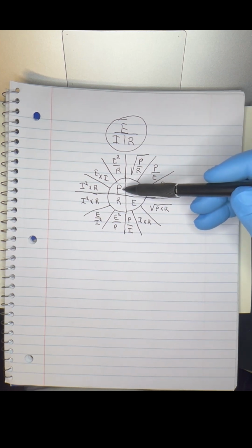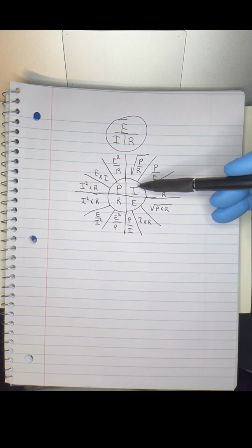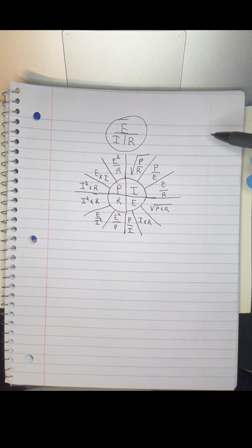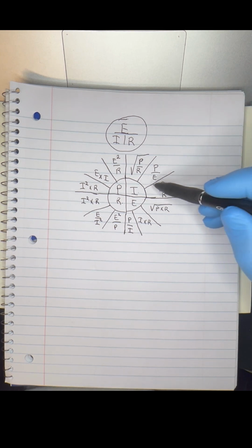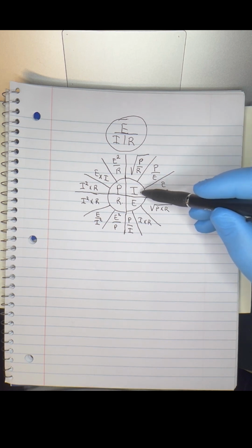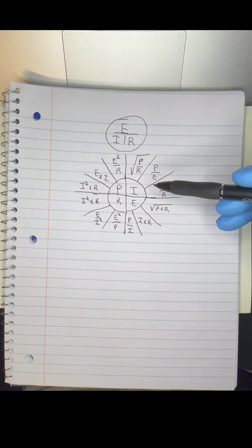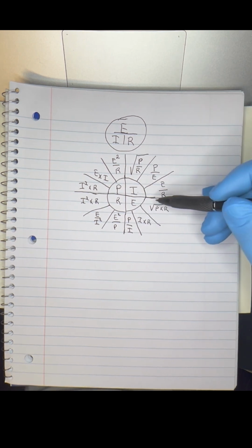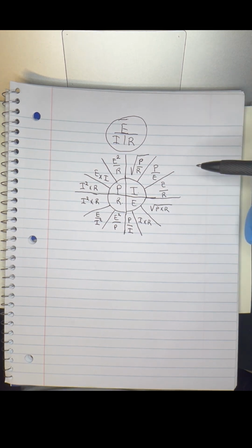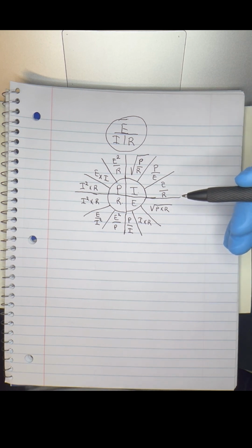And power is gonna give you your starting current, which is I, your full load current, or FLA, of the motor, which translates to I. And with I, you need to calculate with the appropriate voltage, E, what kind of circuit, as far as wire size, fuse size, overload size,